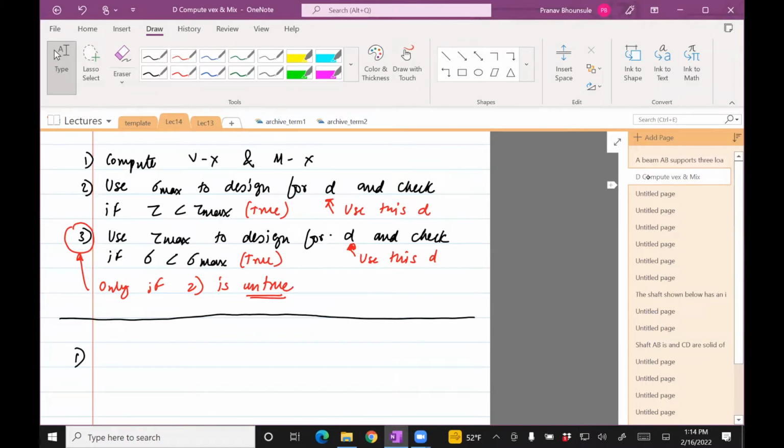Yeah, that's right. So that gives you 3 unknowns. We have only 3 equations, right? Fx, Fy, and M. You need to assume a pin joint on one and a roller joint on the other one. That way you'll get 3 unknowns. The pin would have two unknowns, and the roller would have 1.